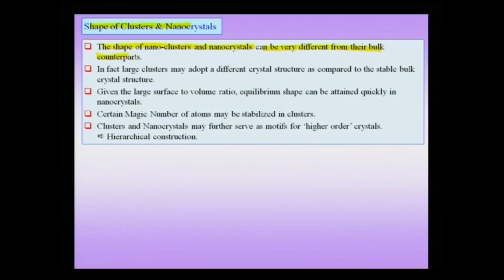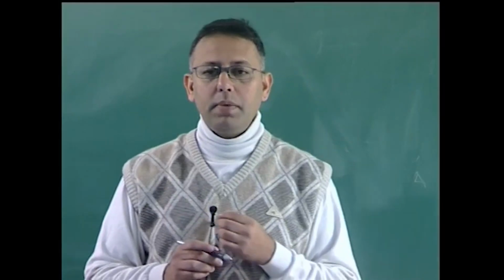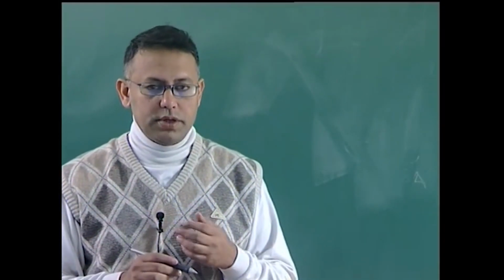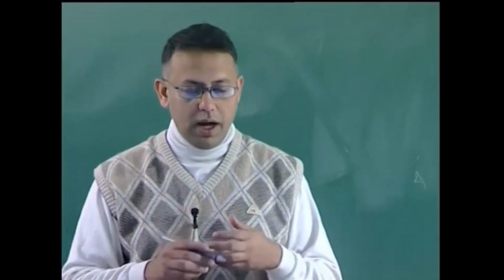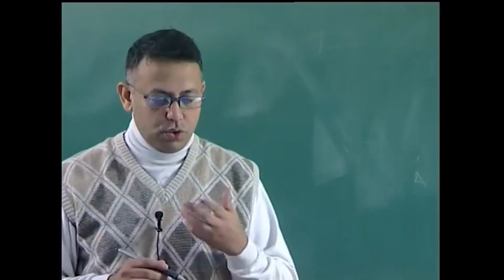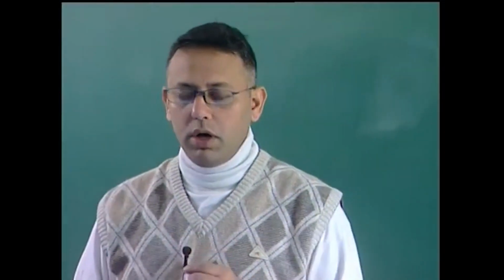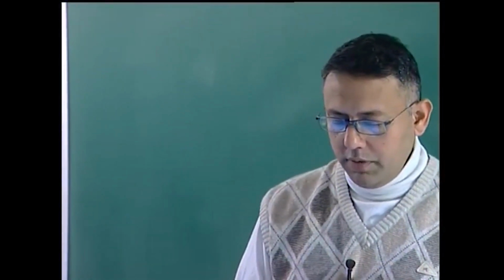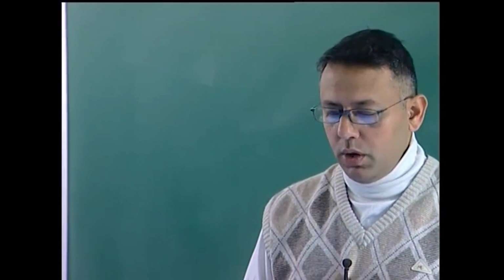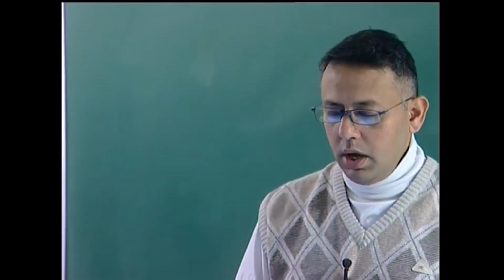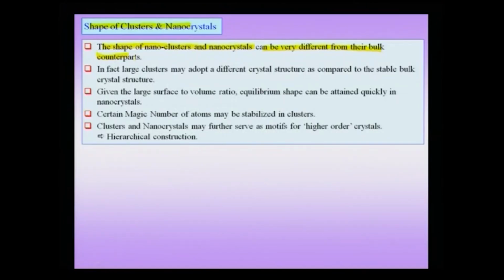And now we are talking about the shape of the external polyhedra which forms in the equilibrated shape, which we have seen we can obtain from a Wulff construction, but a Wulff construction typically applies to large crystalline, macroscopic, tangible bulk crystals rather than to these small clusters. And therefore, I may have a Wulff construction for the nanocrystal or the bulk crystal, and I may have these clusters, and these two shapes typically are very different.